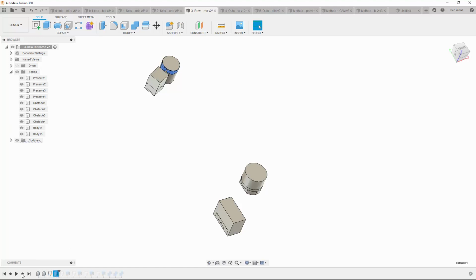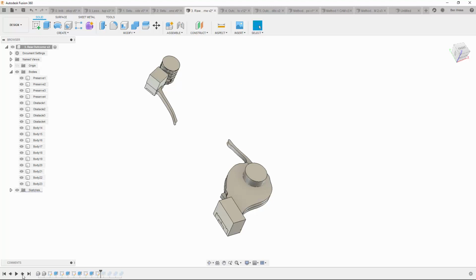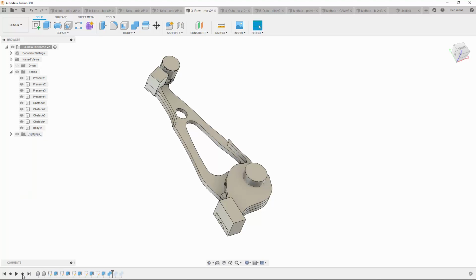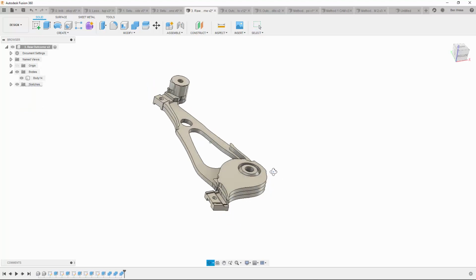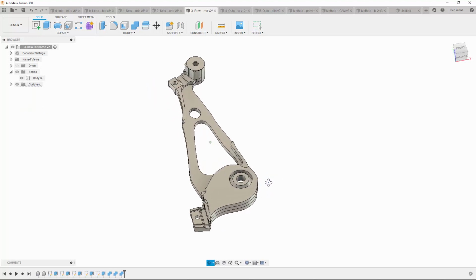That generates the geometry for the first layer. Sketch extrude gives us the second, sketch extrude, the third. There's the extrude at the bottom now. And we can see that this just slowly builds up the geometry that we want to create. Finally, there's 3 combines. The first merges the layers into a single geometry. The second subtracts out the obstacles. And then finally, we union in the preserves.